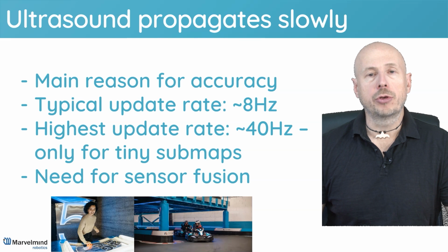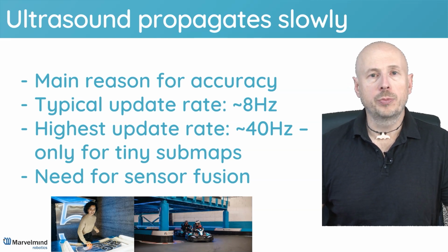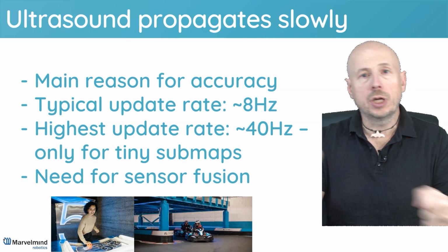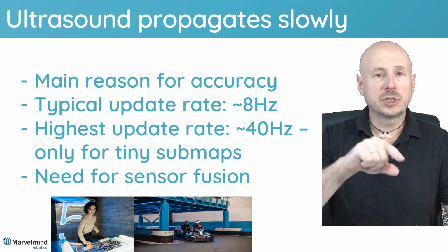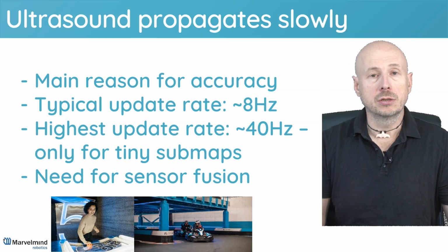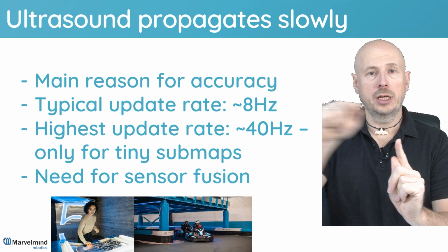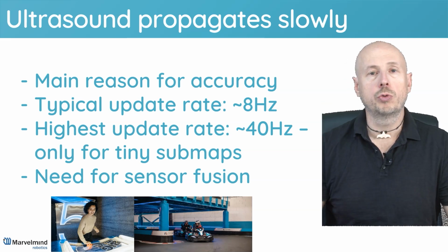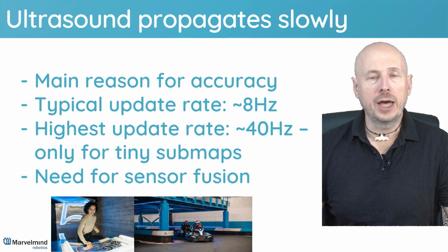But for example, if you have a larger map, like 30 meters, you'll have around 11 Hertz theoretical limit and 5, 6, 7 Hertz practical. And if you have a very quick cart moving, that would mean that the dots come too rarely, and if the object is moving too quickly, some data points may simply be missed. So instead of a curve, you have one location and another location, and this location in between you simply don't have because it was so quick. If you have a smaller map, you may, purely based on ultrasound, achieve a high update rate.